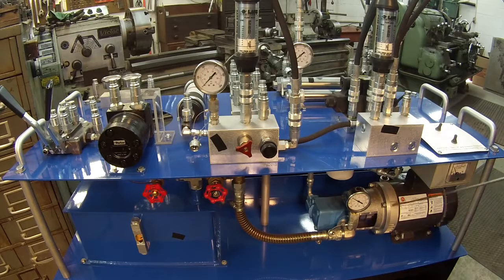Misalignment. If you misalign the shaft of this pump right here, you can pull air in through that shaft seal right there, and you can damage your pump. So misalignment is very important. Soft foot, obviously, back here on your electric motor. And then your RPM going too fast or too slow. That can affect your gallons per minute coming out of your pump. Alright, that's your prime mover.